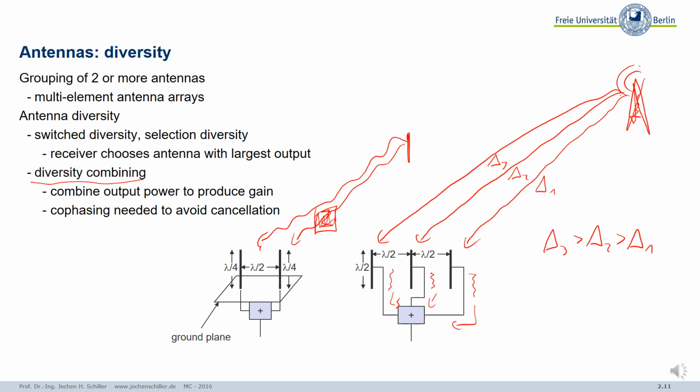So you see how nice this all comes together. In 1 nanosecond, your sine wave travels in one period 30 centimeters. So you can really make the phase shift visible. If you have your antennas some centimeters apart, you have already some phase shift, which is reflected in some degrees of your nice sine wave.